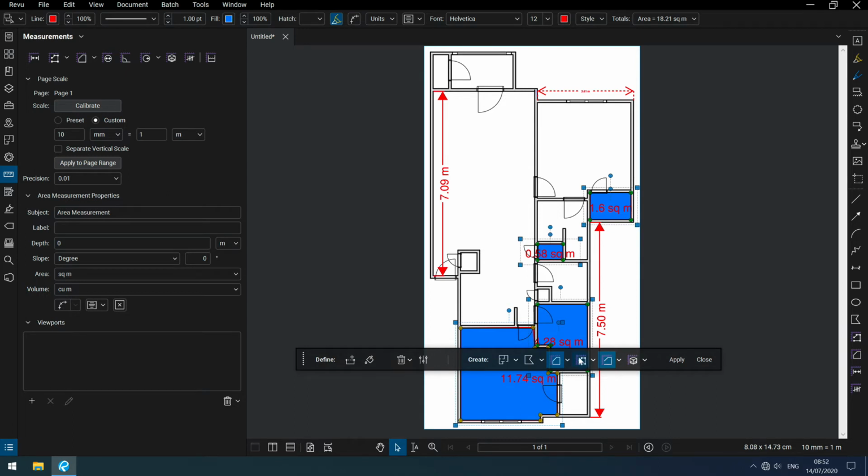And as you can see, it looks a little bit more complicated than the other measurement tools. In this case, it's not a simple click and drag. You actually have to click a few times, but those few clicks are going to save you a load of time. The dynamic fill tool works similar to the magic fill tool in Photoshop, where you basically click somewhere and all the surrounding areas are selected until the selection comes to part of the drawing. When the selection starts touching a drawing, it will stop. Just very quickly going to show you how that works.